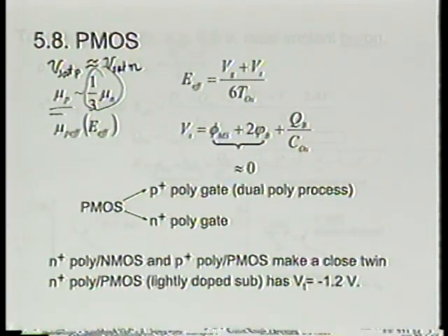Is that right? And in reality, do you know what has happened with all the device scaling today? What is the ratio between the IDsat of N channel transistor and P channel transistor? You know, is it becoming close to 1? It's not, all right? It has stayed about 2 and fluctuating, in fact, a little larger than 2. So the gap is not closing that much.